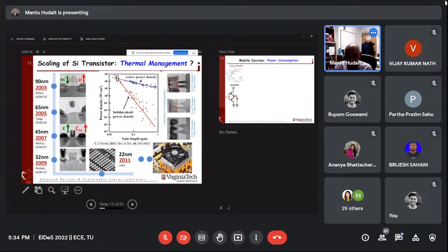That means each processor or each transistor operates around 1.2 volt when you teach the class. But the current FinFET transistor on the right-hand side, where I put a picture of Intel's 10 nanometer, third-generation transistor, I don't have it. At least for the 14 nanometer I have, those transistors operate at about 0.66 to 0.7 volt versus 1.2 volt.